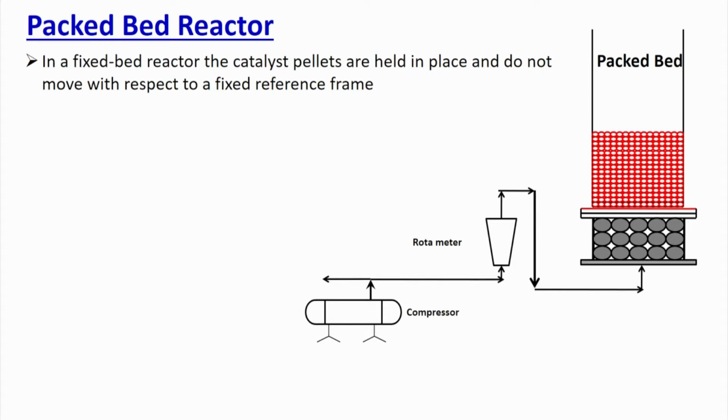What we do, we dump the solids inside the column, inside the reactor. Say this is my reactor vessel. We dump the solid, though I showed a very systematic bed, but generally the bed is not that symmetric. You dump the solids and it forms a certain shape inside. The only thing is you operate it at a velocity such that the bed will not move. It is lower than the fluidization velocity or minimum fluidization velocity. So, solid will be in the packed form.